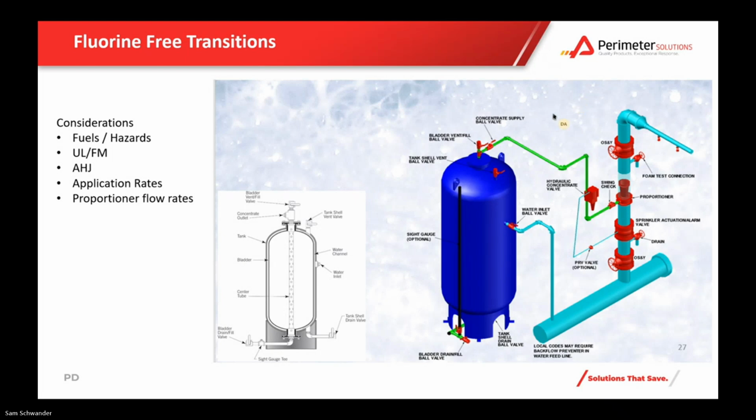So just as a summary on change outs, I know there are a lot of questions, and in many different states there are different requirements on timelines and changing things out. So again, in a perfect world, keeping in mind that a foam system is a kit, as best as we can, we want to maintain the listing, being consistent with the manufacturer and using a sprinkler head that's listed with the foam.